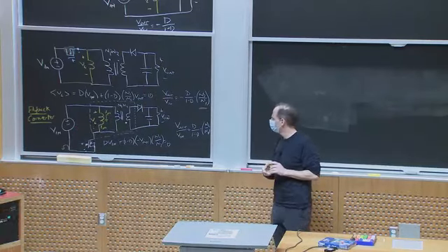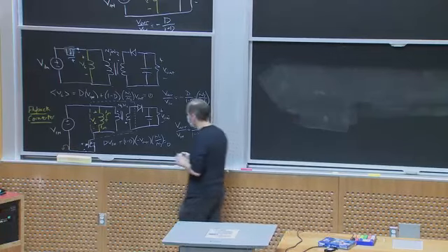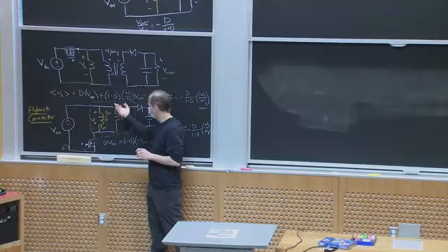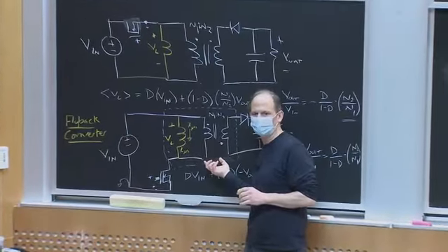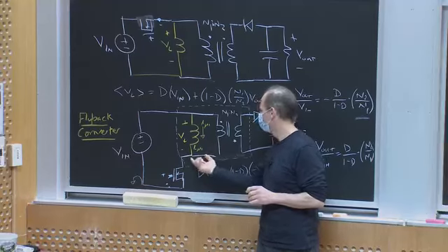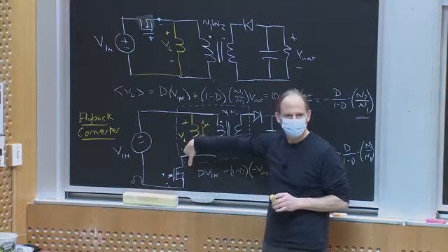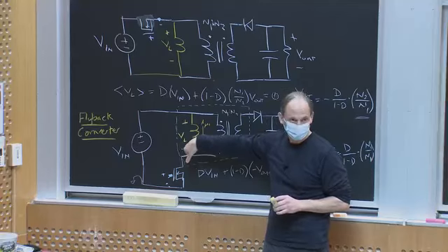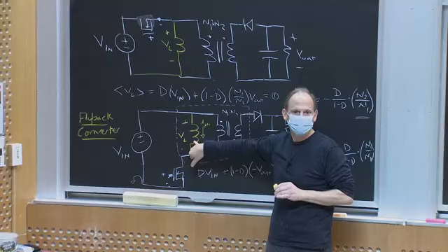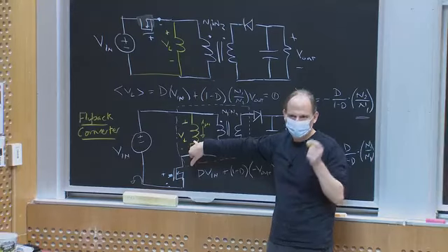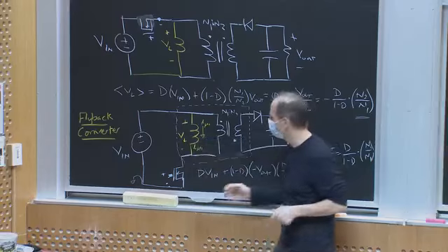How would I design the transformer for this kind of thing? Well, what we would want to do is now, like an ideal transformer, I don't want any energy storage in it, right? The magnetizing inductance, I usually want it to be infinite if I can make it that way. But now, keep in mind that in this converter, this yellow guy here is our energy storage element, right? So if I'm going to store energy in it, I usually would like to gap my magnetic structure so that it can efficiently store that energy in a small space, right? Because we put the energy storage in the gap.